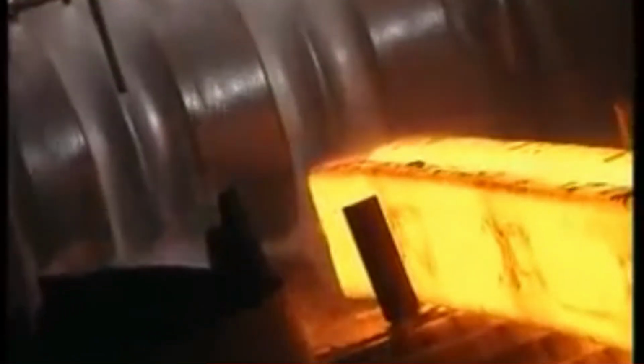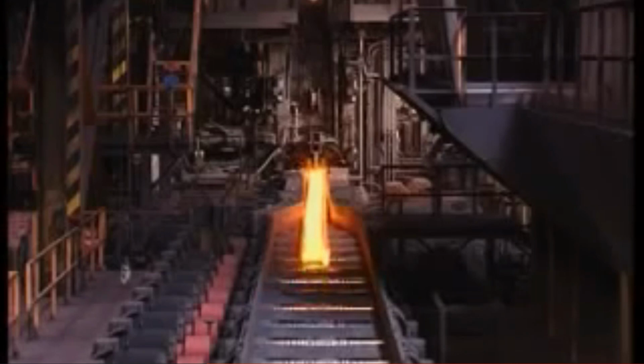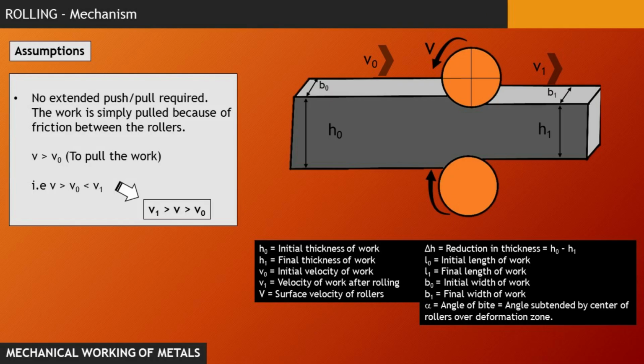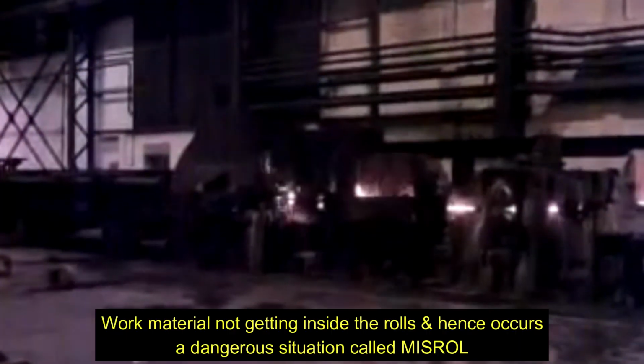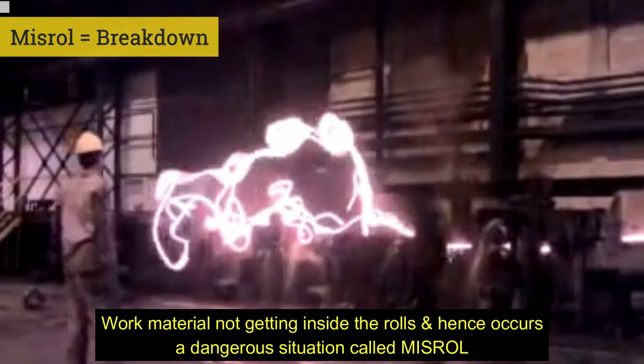The work is simply pulled because of friction between the rollers. Or we can say the surface velocity is also greater than the entry velocity of the work material, and this is a required condition to pull the work. Otherwise, the work will be stuck between the rollers and we will get a breakdown of the rolling mill.